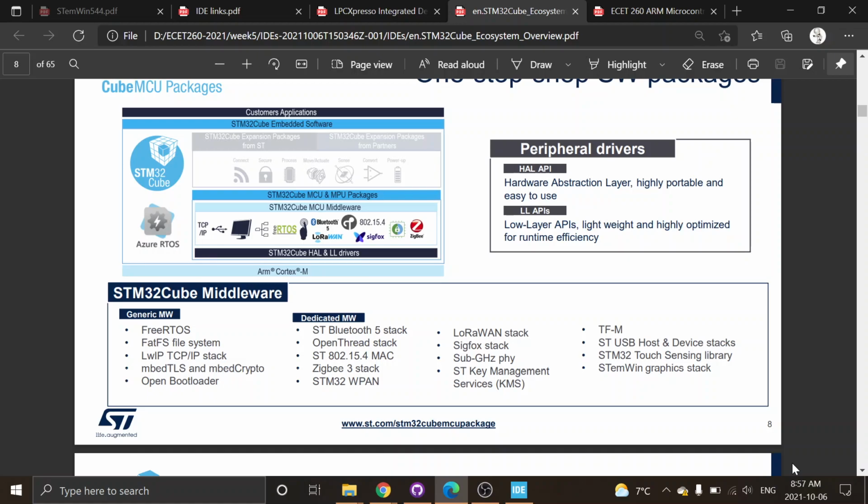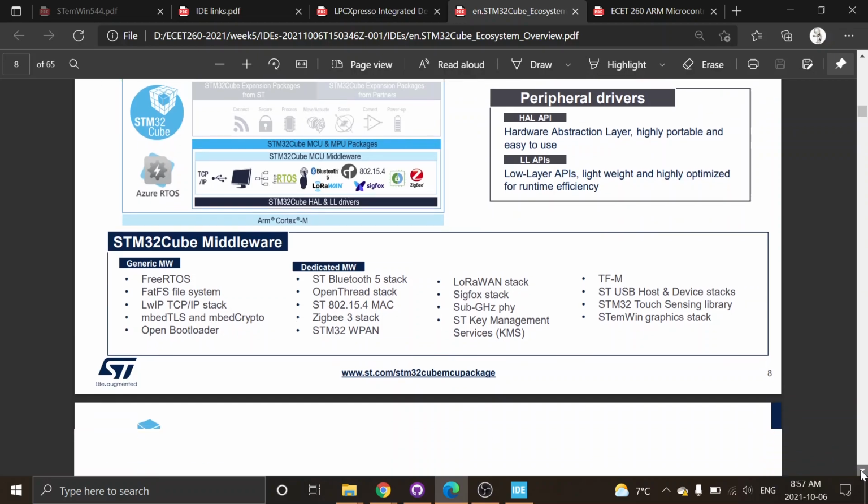Depending on the ST chip, you can also get TouchSense. One of the project groups is building a synthesizer, and they're using TouchSense with an external chip on the one that they're using. But you're wanting a capacitive touch, so you just put pads. You could even put pads under glass and then have it recognize them like they're buttons. And so certain ST boards, the chips are able to have that advanced A to Ds that understand that capacitive touch. And so you can use some of that as well.